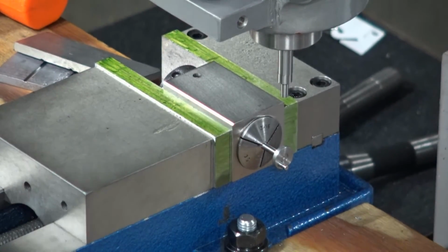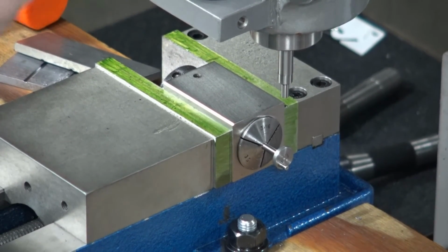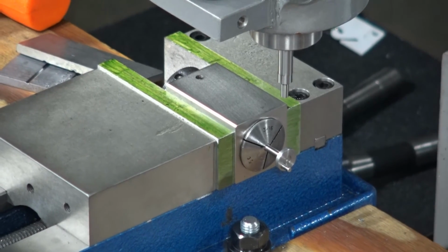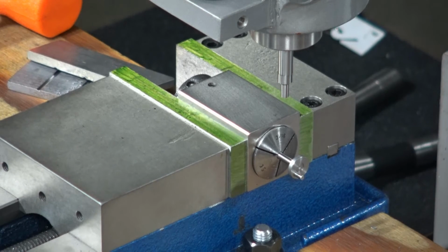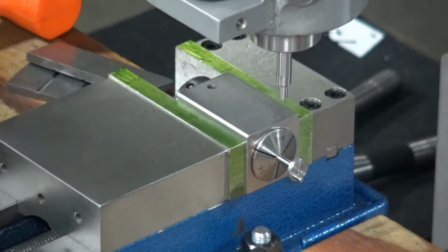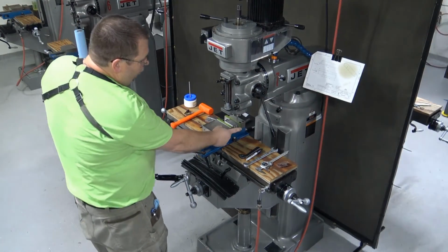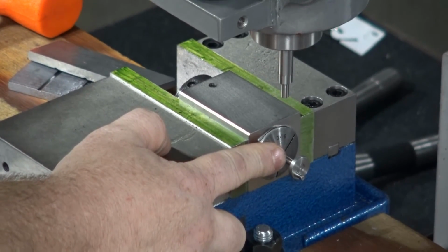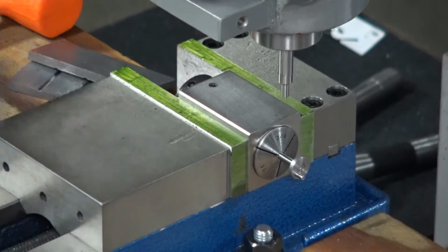We've already calculated during the whiteboard that we want to go 520 thousandths plus half of the slot width. So 520 plus 95, which gives you 615 thousandths. We'll go back over this hand wheel. 2, 4, 615 thousandths. Now I'm going to go ahead and lock my table in. So now we've moved from the face of the crankshaft to the center of the flat that we're going to machine. And now we're ready to switch tools out.